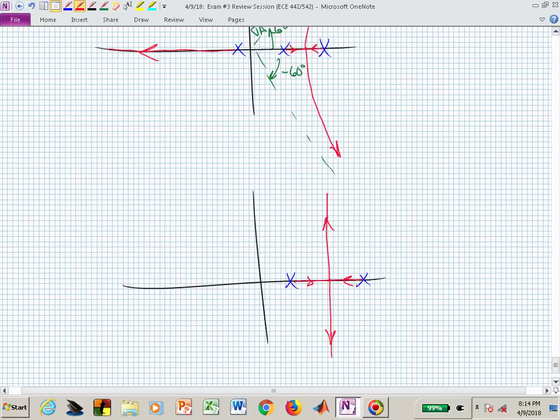So in this case, the asymptotes are at plus and minus 90 degrees. They're 180 degrees apart. They split 360 in 2. When you had 3 branches, they split 360 3 ways, and the fundamental angle from the real line is 180 divided by 3.